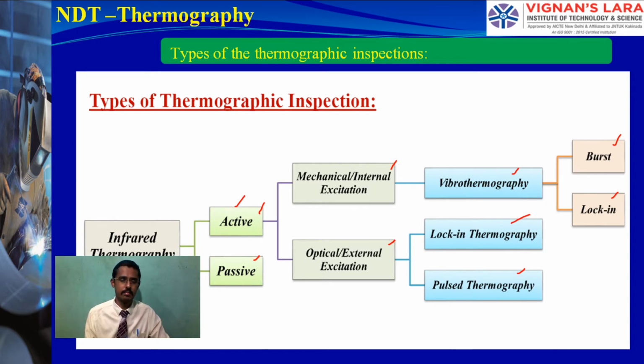When it's coming back, I'm using either active methods or passive methods. In the active we have internal and external, which are again subdivided. As of now, in this classification of the active method, I have taken the external excitations. On that we are going to see pulse thermography and lock-in thermography.